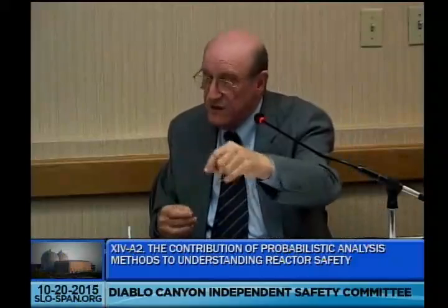The key is that once you've got this thing all designed, you've got to analyze accident sequences that, despite all of your efforts, lead to this core melt accident you don't want, which is undesirable, and then the release later, which is undesirable. Those things are not incredible. They, in fact, have understandable probabilities and understandable consequences, and an analysis was developed in 1973, 74, 75, it's called PRA, that demonstrated that, in fact, this was so. And the key is identifying accident sequences that go all the way to the end of the disaster.